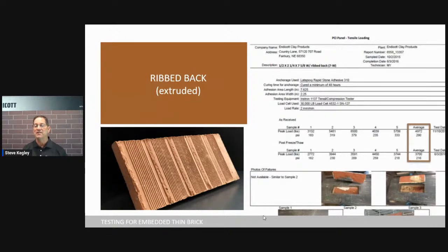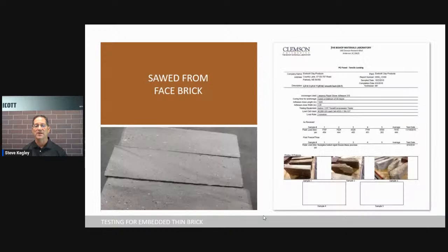And you can see that the pull-out strength is 290 before they put it in the concrete and tested it. It was still 216 after the fact. Now their code, the specification calls for 150 for pull-out. So we're exceeding either one of those, in either application there.